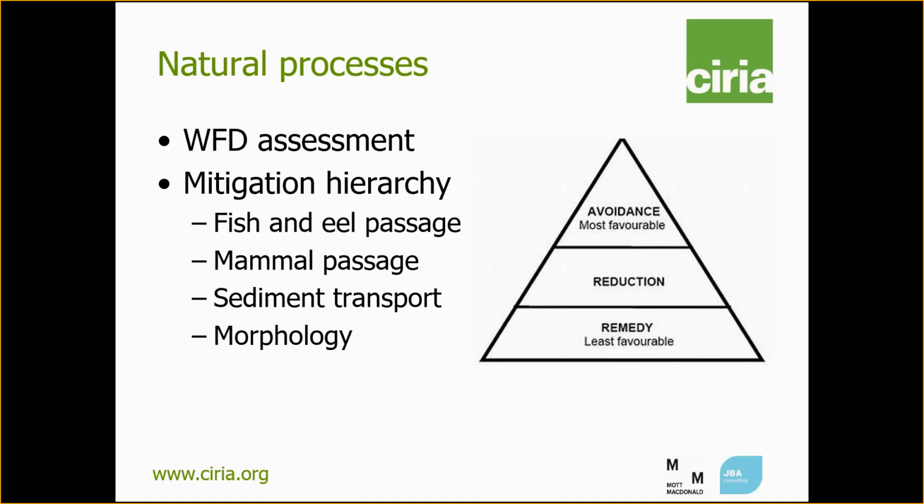The fish passage guidance is based on the Environment Agency Fish Pass Manual, which is now published by the Institute of Fisheries Management. And it also discusses the potential behavioural obstacle presented by a dark culvert, and concludes that the installation of light wells lacks compelling evidence. So it suggests providing wider wing walls, pools or resting areas at the transition from the natural channel to the culvert to ensure that fish aren't discouraged.